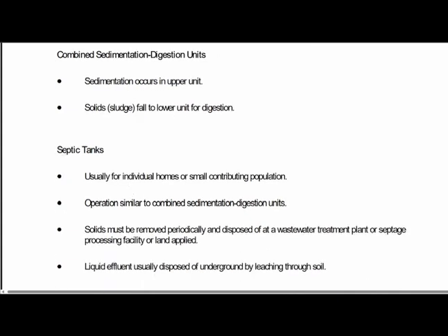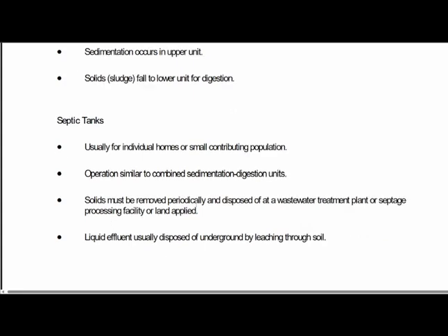Septic tanks are usually for individual homes or small contributing populations. Operations are similar to combined sedimentation and digestion units. The solids must be removed periodically and disposed of at a waste treatment plant or septage processing facility or land applied.